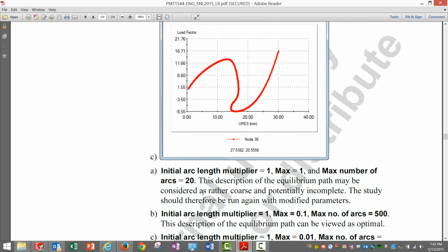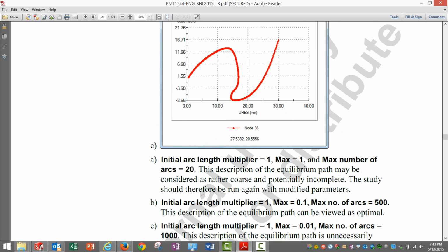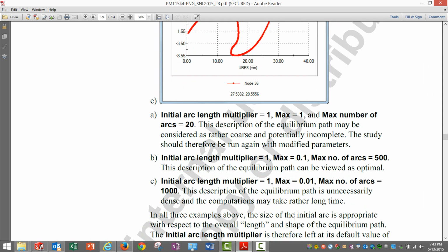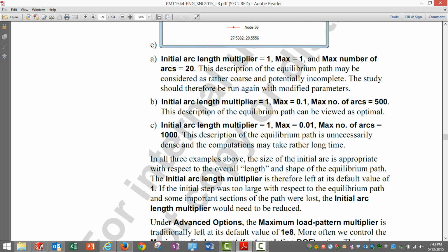Definitely, looking at the top graph, it appears A could be a bit coarse analysis. If I want far more accuracy, B sounds good. C would be very accurate, which may not be necessary, but just to get a feel of how it looks, you can do this analysis. All said and done, it is difficult to interpret these parameters before we start off doing some coarse analysis. So better do it and then get a good feel of it.